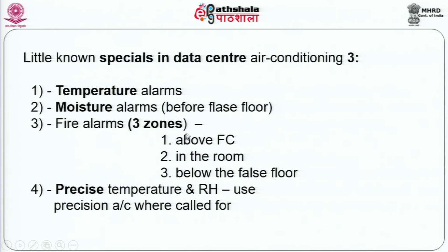These are of course I think very common and very necessary, and very rarely precise temperature and RH controls, because today equipment, as I said, has a very large control width from 15 to 25. So precision is never required, plus or minus 2 degrees is good enough.